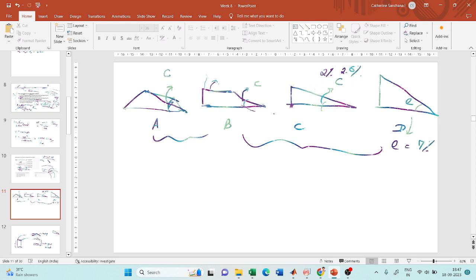Here my entire super elevation has not been achieved. Though the shape of the super elevated portion has been achieved, its value has not been achieved because this is just 2% slope. Now I have to take it to 7%, only then at the start of the curve the super elevation for the curve has been attained, right? If the curve requires a super elevation of 7%, then I have to provide 7%. So till I reach that 7%, I will keep increasing this, right?